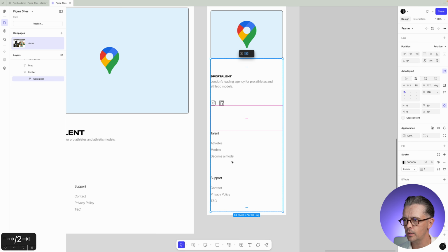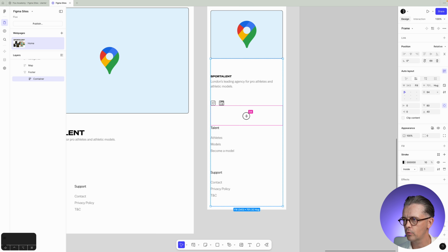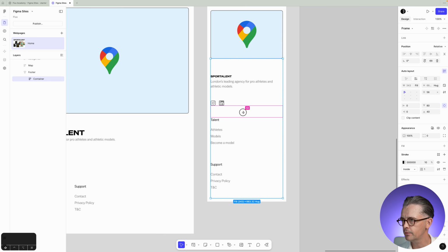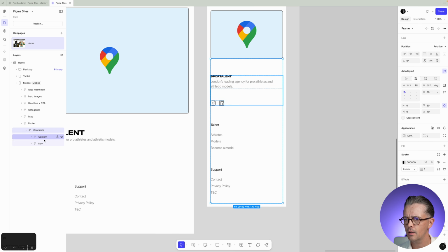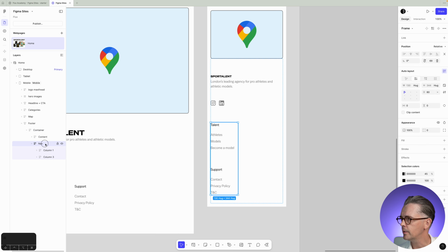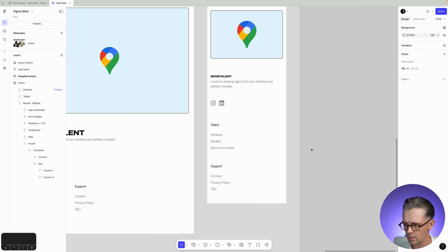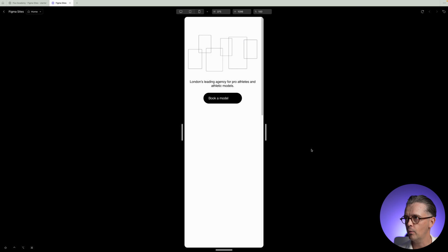And then the space between these things here, which is currently 120, I can actually drag that. Hold shift and drag it in my increments. We make that 80. And then in the nav, the space between these two is currently 80, so maybe bring that down to 64. Okay, I think let's have a look at that and see how we're going.